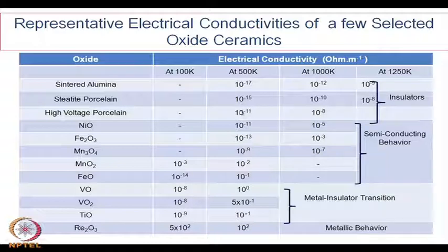and you will find the insulation property, or the conductivity, increases as we increase the temperature. That is the normal behavior of an insulator as well as the semiconductors here. Only difference is the conductivity of semiconductors is at a slightly higher level than the insulators. So, these are the transition metal oxides, and because of the particular defect structure and the concentration of point defects and resulting non-stoichiometry, we do get semiconducting behavior in the oxides.